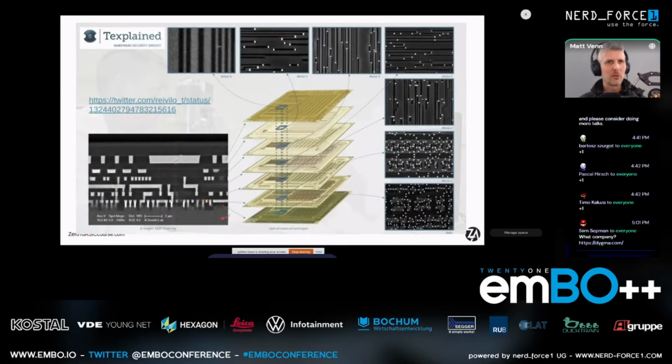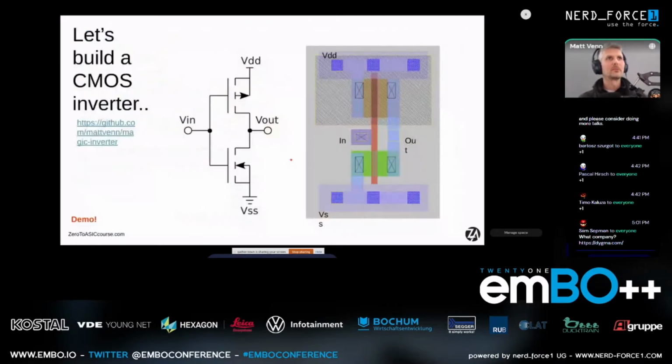So at the bottom here, we've got our operational layer where the MOSFETs are. And then we've got 1, 2, 3, 4, 5, 6 metal layers that go on top. And you can see the way they're arranged: vertical, horizontal, vertical, horizontal, vertical, horizontal. And these things patch together all the devices into the working structure that we're trying to build.